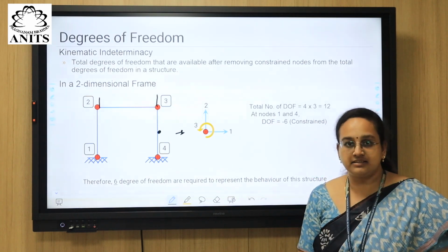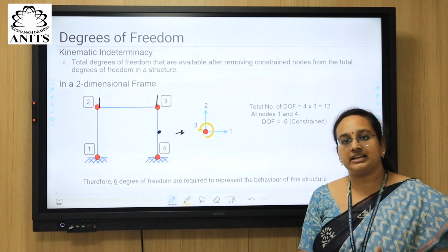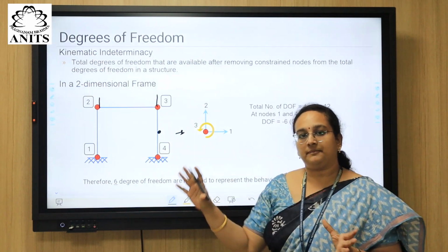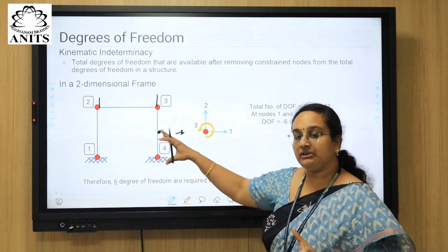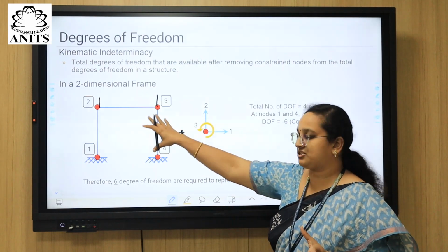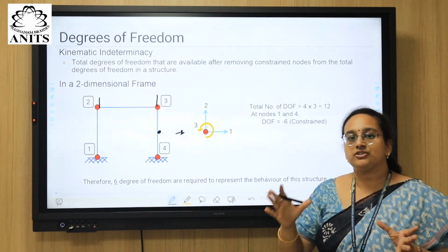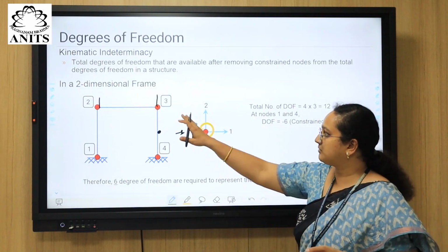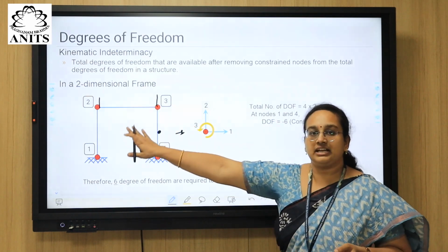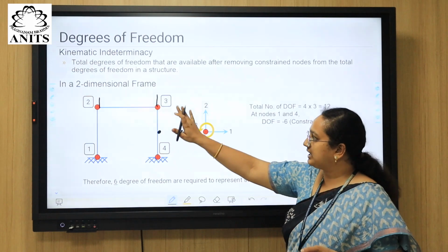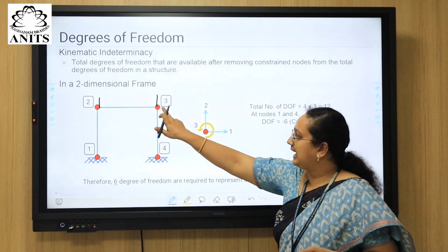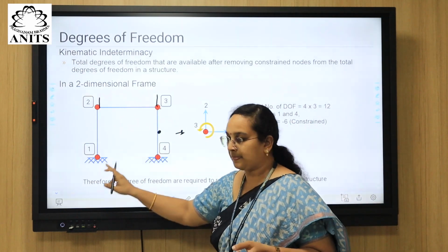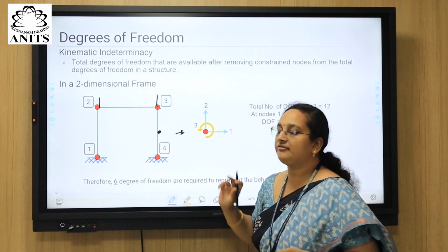Why do we need the critical locations? Because we need to design the building. If we design for the critical ones, all the stress resultants in between these critical locations can be taken care of, right? So that is our main agenda, to design a structure. Tracing it back, we can define the nodes at the locations where we are interested. So this is a plane frame where we are interested in only 4 nodes.